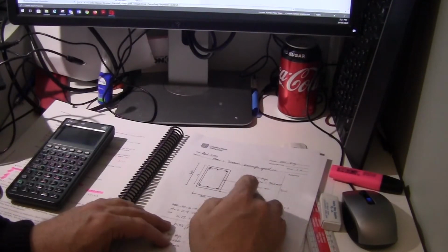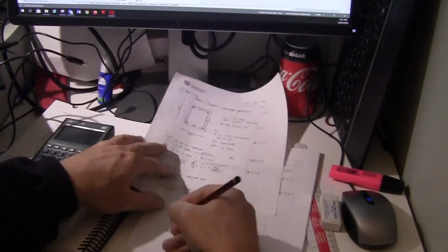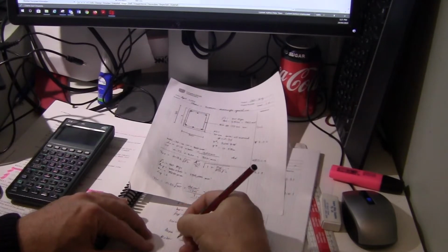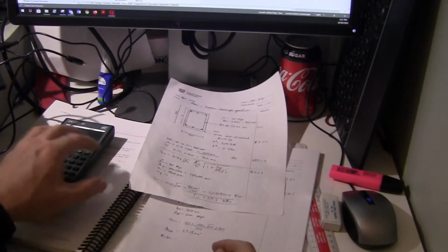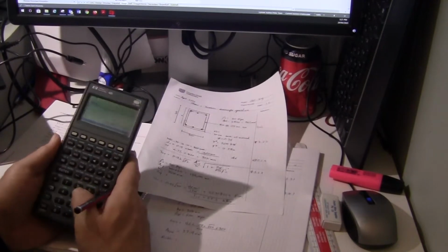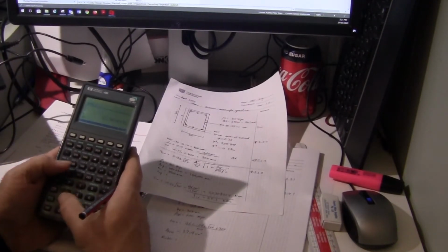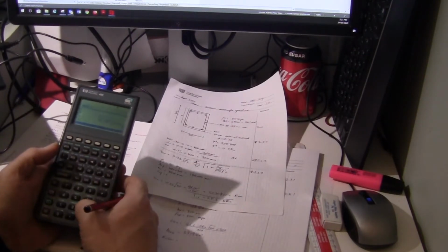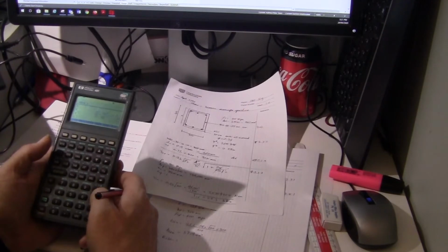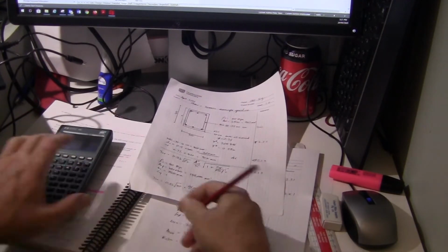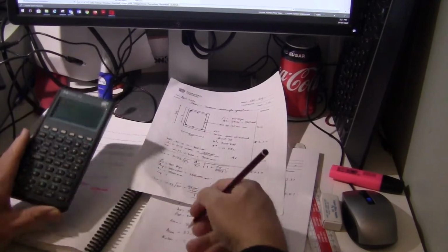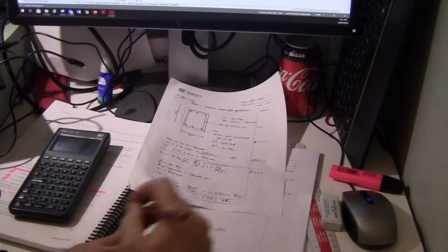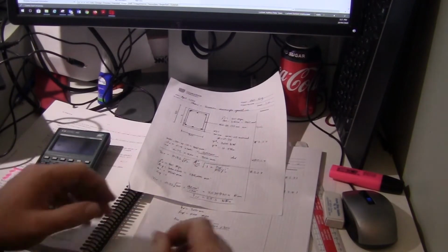All right, let's see how much steel we've got. We've got N10 bars. Each of our bars, for an N10 bar, is 10, divide that by 2, it's a 5 millimeter radius, we'll square it, times pi. And then we've got 2 of those, 157 square millimeters. So we are comfortably more than the minimum steel.